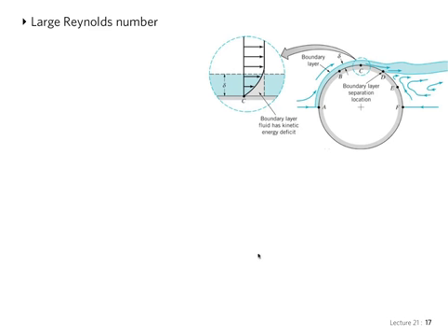Okay? And what we have is that if we're looking at the same situation that we had before, a particle going from point A to point C at the top, 90-degree angle, back to point F. Previously, we had that particle going all the way around without any loss whatsoever. Now, because of viscous effects, the particle is going to experience a loss of energy due to friction.